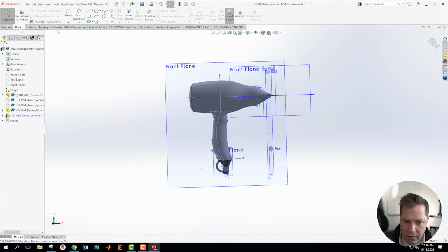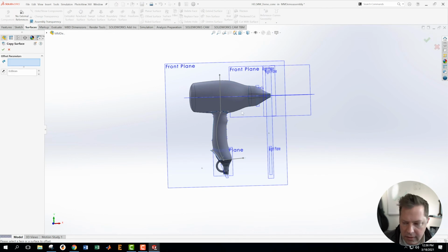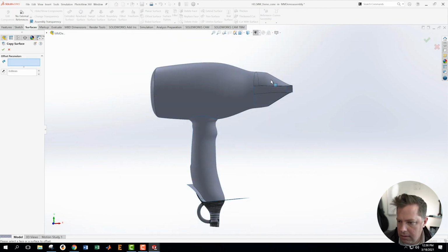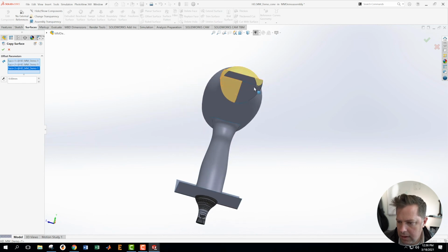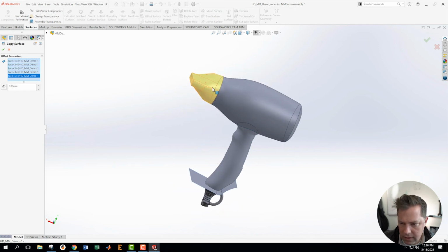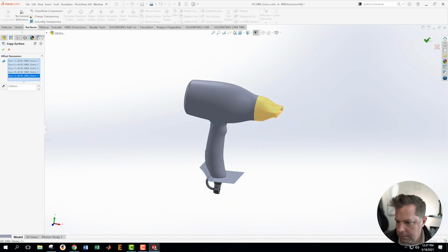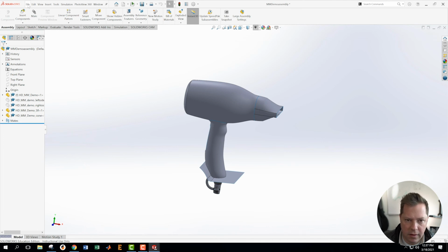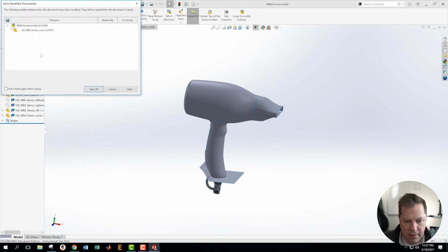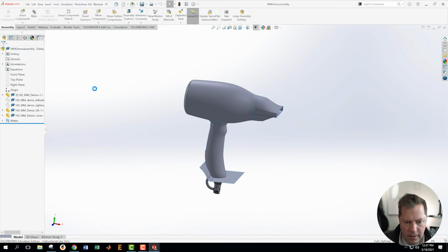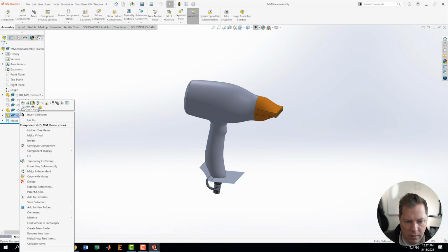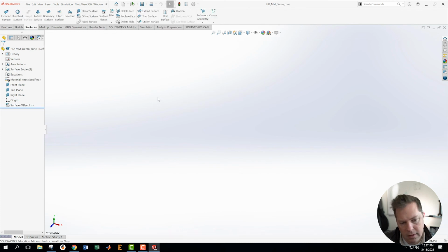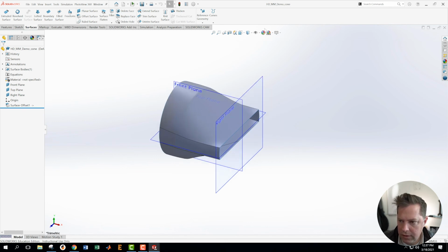Now I'm editing the cone. And in editing the cone, I want to just do the same exact thing. Offset surface, set this thing to equal to 0. Hide those things. And we want to get all of this. Okay, that's it. We're done with this. Come over here, we rebuild. We're going to hit save. Save. We're going to come in here into our cone, and we're going to open our cone part. And we're going to rebuild so that my graphics card will deal with it.